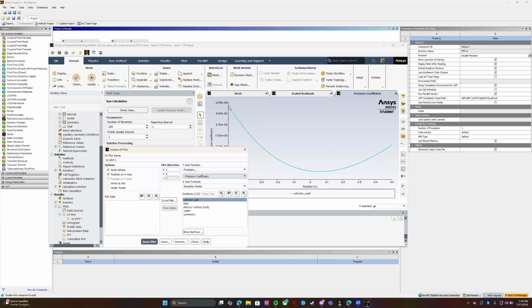Pressure coefficient, we're looking for this kind of little scoop. And then, as you would go, it would go out and kind of flatten out a little bit. So then next, we're going to do our velocity. And you'll notice it's a straight line because of the no slip condition. Since we're taking our reference as a cylinder wall, once we hit that wall, it's like we're measuring the velocity on that wall. Because of no slip condition, we're going to get either very small velocity because there's a little bit of roughness to our structure, or we're going to get zero. So it's going to look constant.